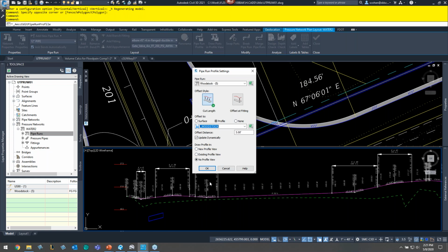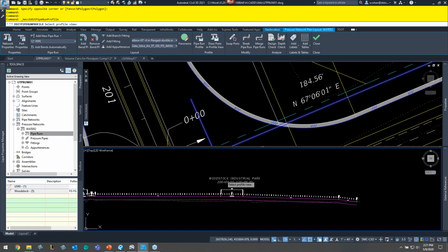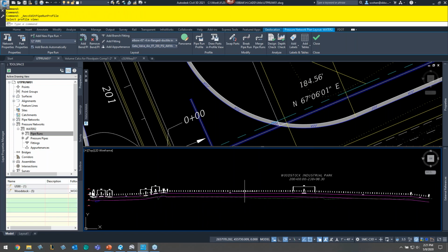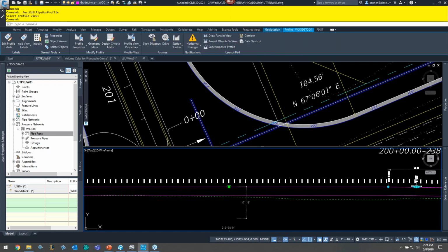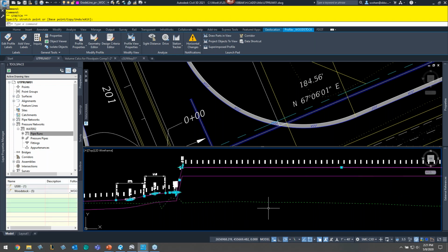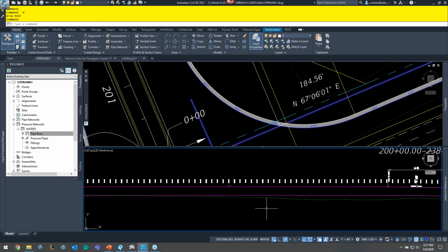Again, this is a road, but it can follow a profile that you've designed within the actual alignment. For the actual profile itself, I actually want to grab the existing profile view, all right, and I'll go ahead and click, because you can create a new one and have it update dynamically 3 feet below. So if I click OK here, notice how it creates that automatically for me, and then I'll pick the profile view. So this in and of itself is the really cool thing, it's already a dynamic profile. If I pick on this profile and adjust it, it maintains 3 feet no matter what. So that in itself is really cool, okay? So forget the pipe run stuff, just having a profile for that is actually really nice, okay?